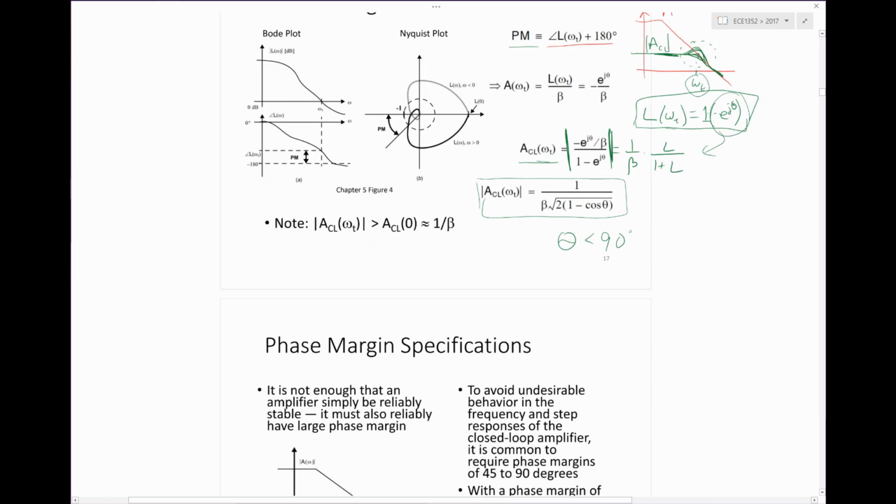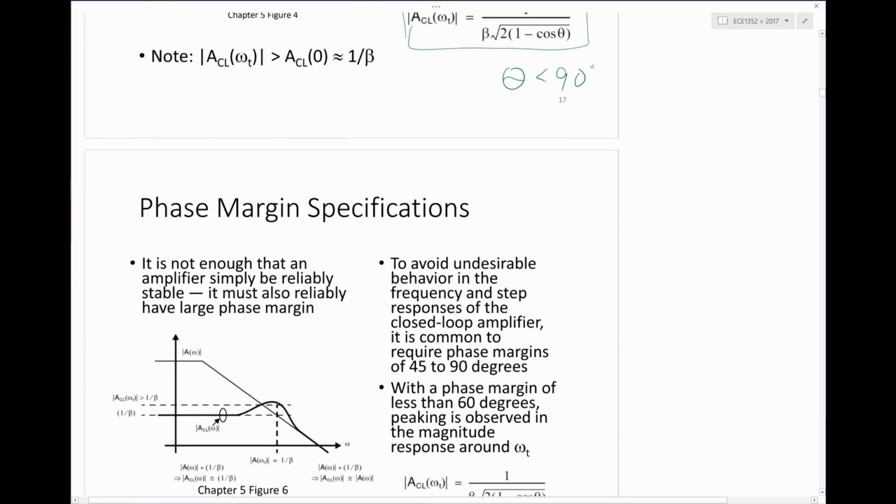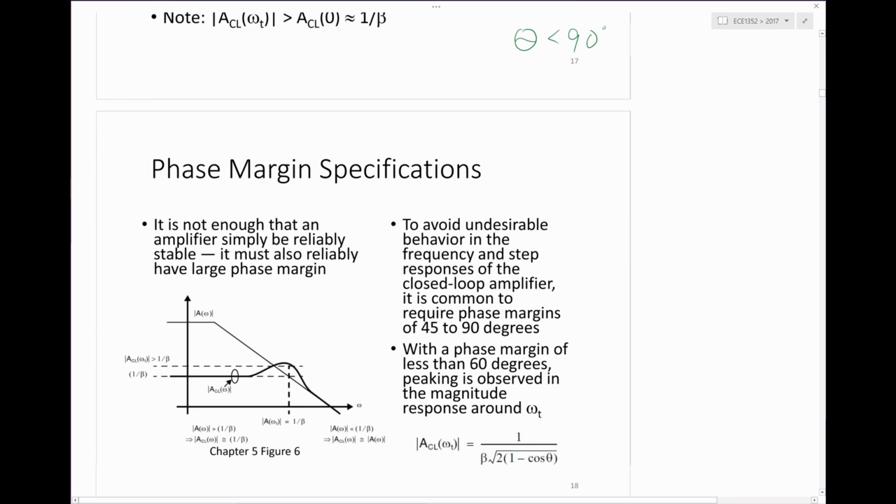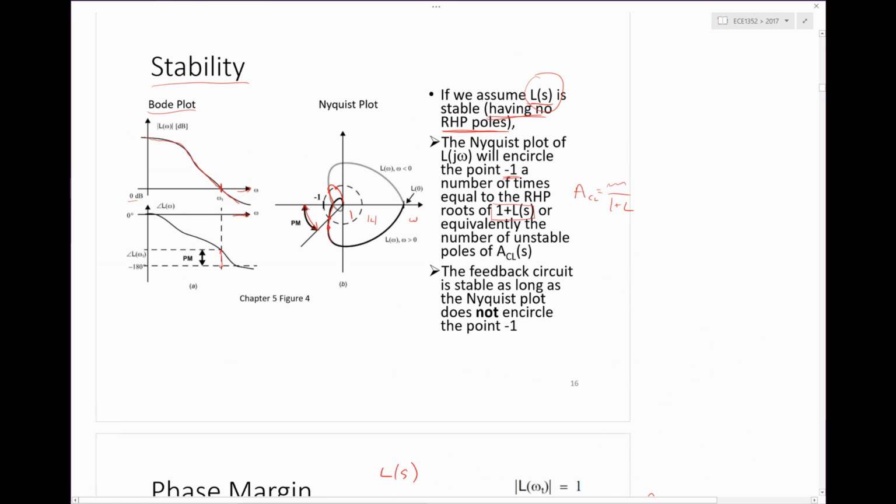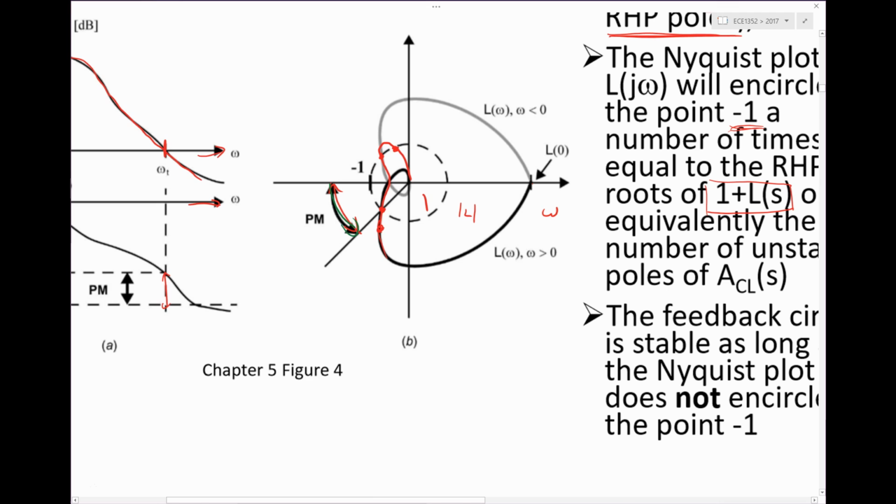So this brings up an important takeaway point. Here's the sketch of that happening. I think you get an impression just from the names we use, phase margin, gain margin, and when you look at this Nyquist picture, you probably have the idea that all of these things are just a safety margin for stability.